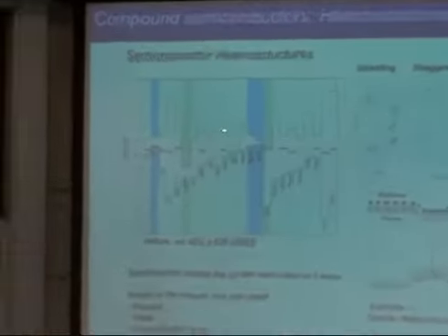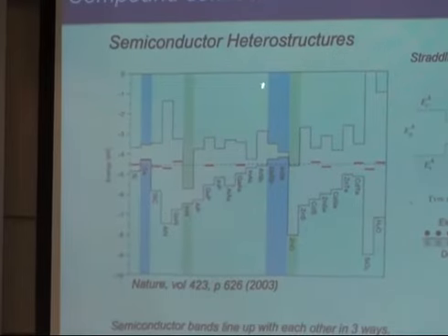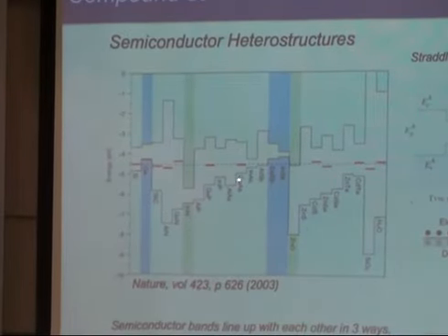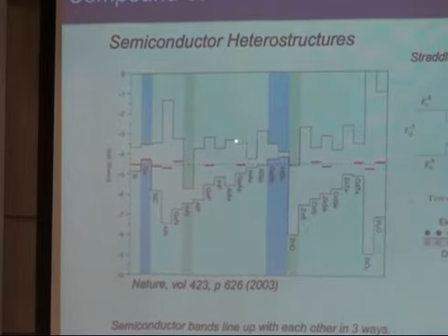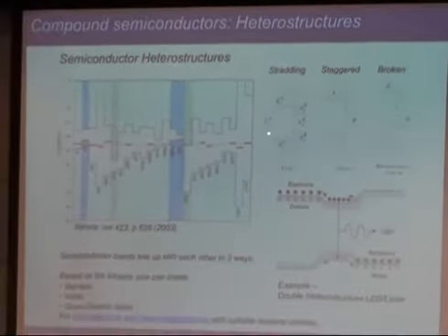So what's shown here is the band edges. This is the conduction band edge, and you have all your spaghetti E-k diagram above it, right? Here's the valence band edge, and you have all your valence bands under it, and all that. So this is the gap, right? And I put aluminum arsenide and gallium arsenide, and there is a band offset in the conduction band, and there's a band offset in the valence band. And band offsets look like this, and I think you realize this is the energy band diagram. This is not the band structure, meaning this is the energies as a function of distance, right?